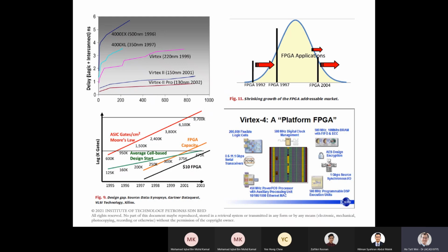It's not just programmable logic. You actually have, let's say, a high-speed serial transceiver. Some of them can do PCIe and all that. This is not programmable logic at all. It's a very dedicated circuit block. It probably has some programmable DSP. It's got dedicated RAM. They're not using the flip-flops anymore. There's actually a dedicated RAM inside the FPGA, and then clock management, so you can change the clock and all that. And then some of them also have dedicated processors. It's no longer that I synthesize the processor and implement it in terms of FPGA logic. Nowadays, they include dedicated processors in the FPGA.